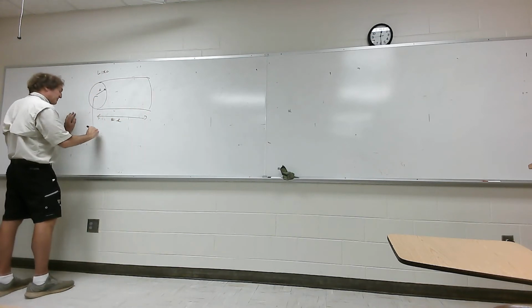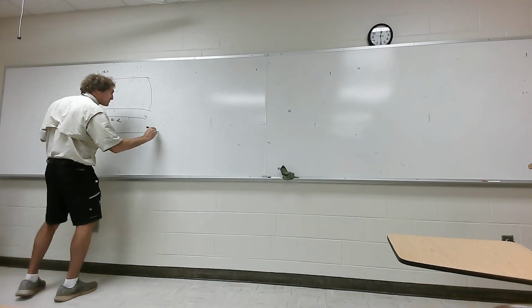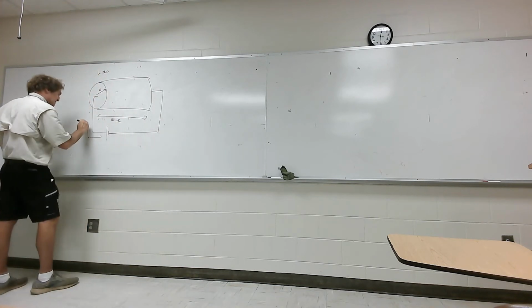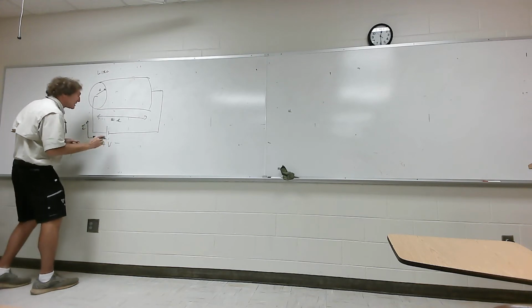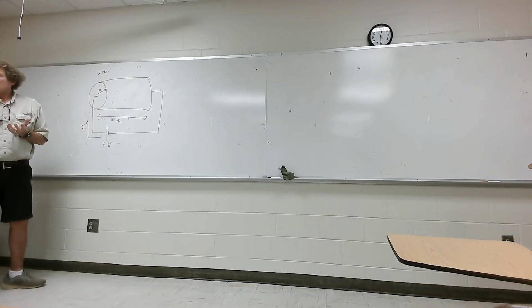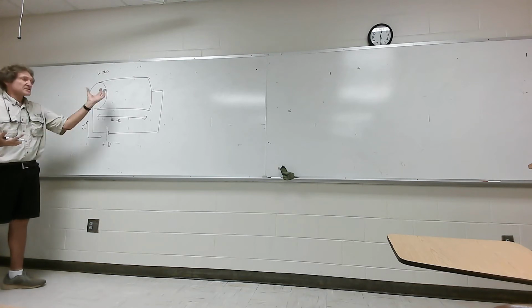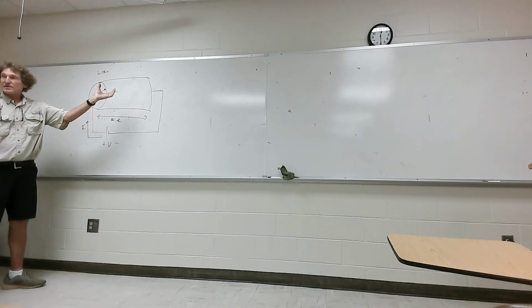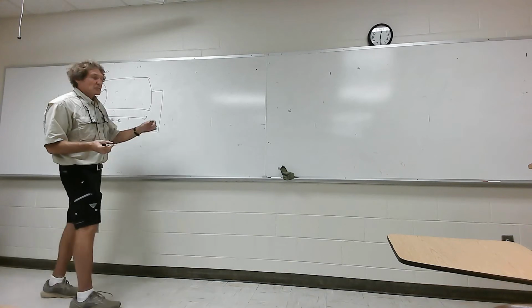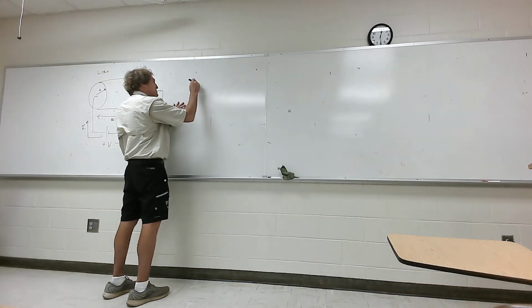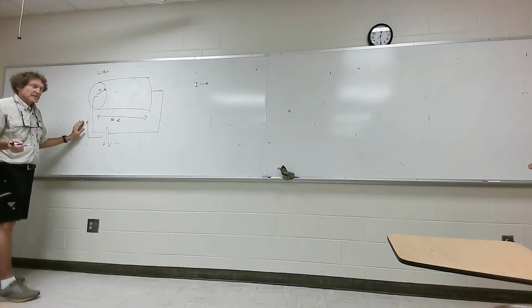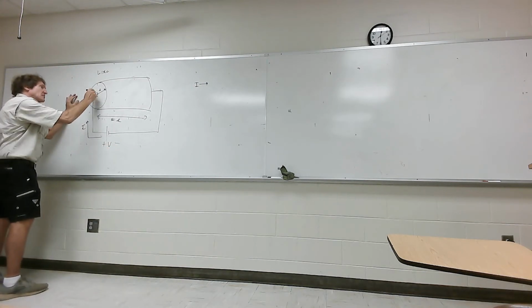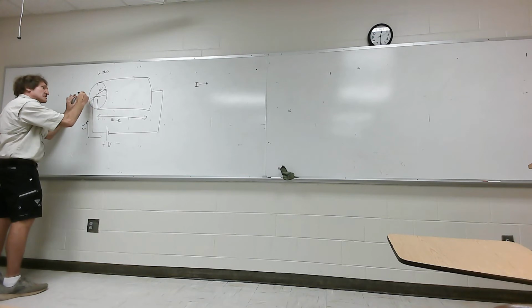As you think about it, if you attached a battery here and drove current this way, there would be a voltage here. This is the standard problem you did in EMAG 1, right? It's a constant cross-sectional area, long rod, that's all it is. To calculate the resistance, first you assume I. You're assuming you know this.